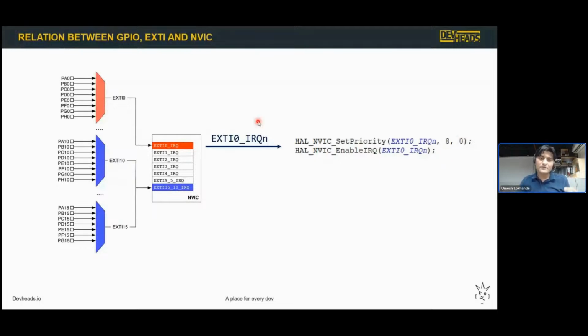Okay, so the first interrupt EXTI0 gets fired because we add these 2 lines of code, and this will come from this PA0 pin, because that's where we are going to connect the first button switch. And this PA0 will get connected to EXTI0 IRQ, and then this will get fired and processed through the code. So let's say for the second button, I chose the PC13 pin, and PC13 comes between EXTI10 down to 15. So this blue interrupt gets fired, EXTI15_10 IRQ.